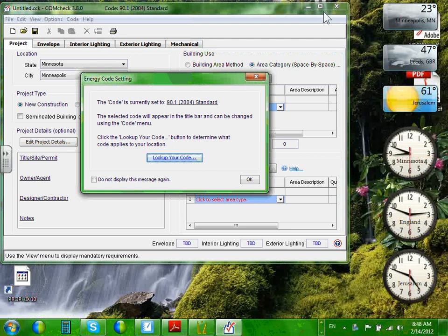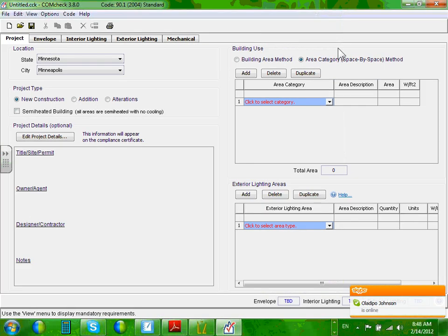Okay, when everybody opened the energy code, COMcheck, can I have thumbs up? All of you have to do that. Okay, when you go there, it will tell you the code right now. It's listed for 90.1 2004. This is what Minnesota is using, actually more stringent than this one. So accept this one as your default and expand this energy code calculation. COMcheck. Can I have thumbs up that everybody's looking at the same screen I'm looking at? Okay, take a few seconds to open it and let me walk you through that one.